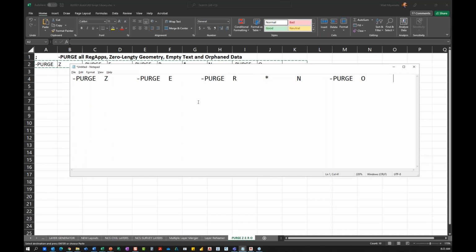And you can see here as well, there is an extra space after the N. If I were to delete that, it would stop on the N at the command line, and that's where it would stop the script as well. So you would see an N pop up at the command line in the AutoCAD session, but when we actually run the script, it won't complete all the way through the process. And at that point, you just hit enter, and it would accept the final command there.